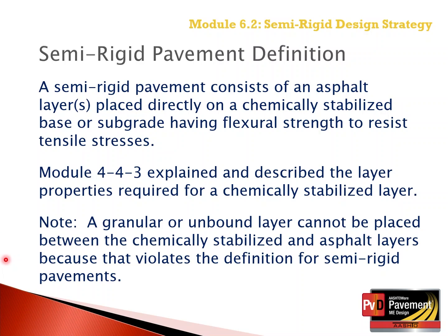It is assumed that the granular material placed between the soil cement and asphalt layer would prevent any transverse cracks or shrinkage cracks in the soil cement, as well as fatigue cracks, from reflecting up through the asphalt layer.